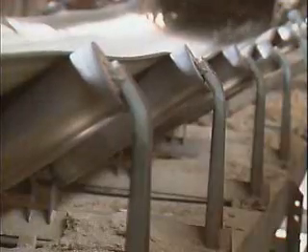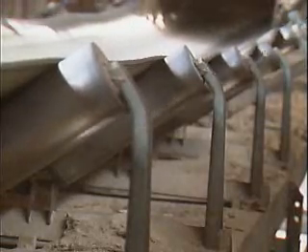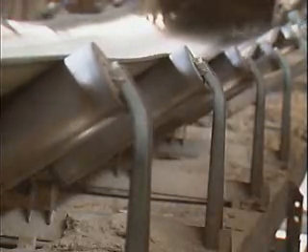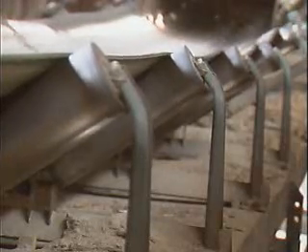There are various reasons for using grease, most of which depend on the operating conditions in a given situation. Under certain conditions, grease may be necessary to ensure that the lubricant will stay in place. As long as grease remains semi-solid, it tends to stay where it's put. Oil is much more likely to flow away from where it's needed than grease is.